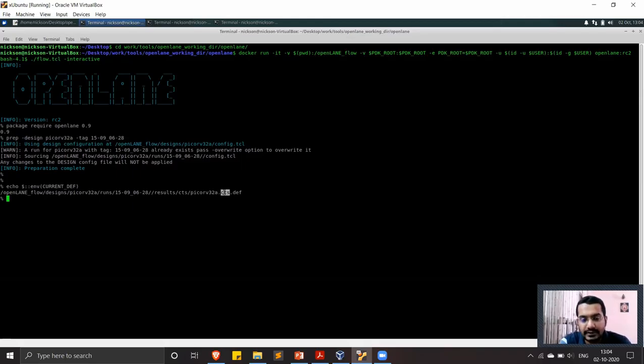So now next we would be doing routing. Pre-routing, if you remember, we still have not completed the power distribution, the power and the ground rails. That actually has to be part of the floorplan, but because of the adjustments in OpenLane, we run this after CTS.